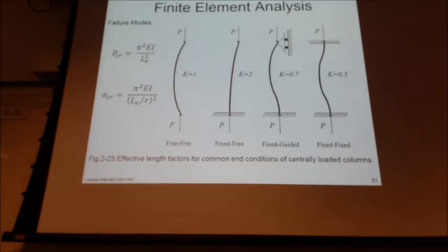We also have to deal with buckling theory, right? So if we have an increase of P over the critical stress, then we're going to have a collapse of the column, and we're always looking for the least radius of gyration as it relates to the cross-sectional area. We have to check that the slenderness ratio is greater than the column constant for Euler's, and then we also have to check the critical stress. Critical stress is governed by the yield strength of the material.